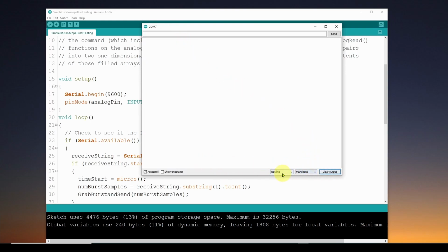And you go down here to the baud rate selection, and you can see you can go from 300, 1200, 2400, 4800, 9600, 19.2, 38.4, 57.6, 78, 500,000, 1 million, and 2 million. Wow! So maybe we can crank up that baud rate to like 2 million and see what happens.